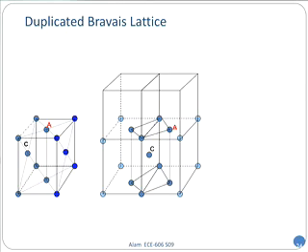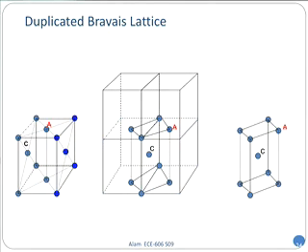Now, look at the A. Okay. Now do you see? So the C, it was on the face, but if I look at it slightly in the corner, the same crystal, instead of looking face on, if I look at diagonal on, then that becomes a body-centered cubic. And as a result, you can see that this is not a new lattice, because it's an old lattice viewed in a different way. So you shouldn't put it in.